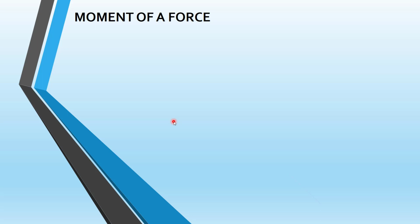In the three-dimensional case, what we need to do is first find the force vector, then obtain the position vector of 2 points. What are those 2 points? The first one is the point about which we need to find out the moment, which is also known as the moment center, and the second one can be any point lying on the line of action of the force.